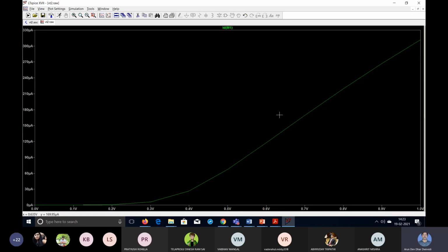You can see it is a 50 nanometer channel length transistor, so all the effects we can see. Even sub-threshold leakage current is there, and in the ID versus VD characteristics we will see channel length modulation is also present. At very low voltage, the current looks almost zero, up to about 0.2. After that some leakage will be there. As I was saying, you have increased the gate to source voltage above zero, but initially, though it was positive, there was no inversion, only some weak inversion. Here you can see some weak inversion is there, and due to that weak inversion some leakage current is there.